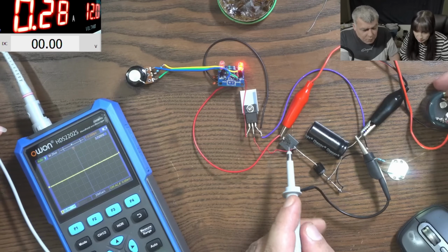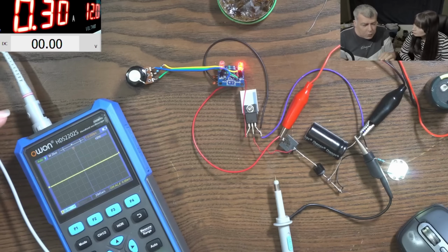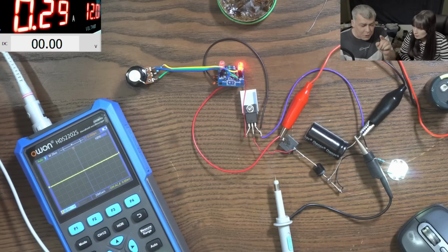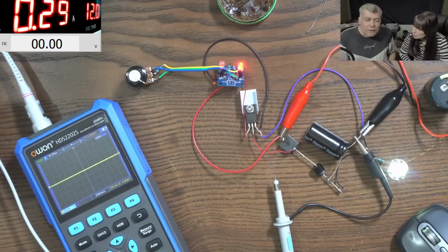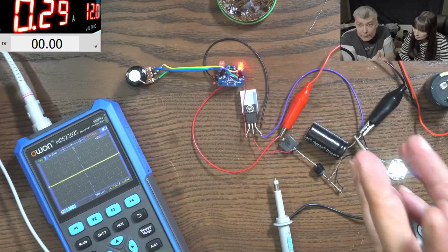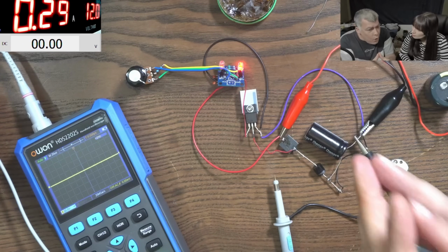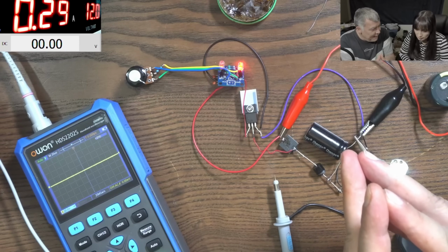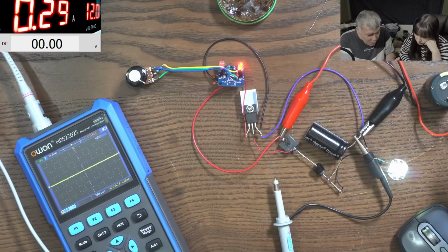So it is better, but not good enough. You can set 200 milliamps, but not 100. But why? Because you need a bigger capacitor? No, really. The frequency is quite high, so you don't really need that big a capacitor. I just told you, the capacitor has to be connected exactly where the noise source is.